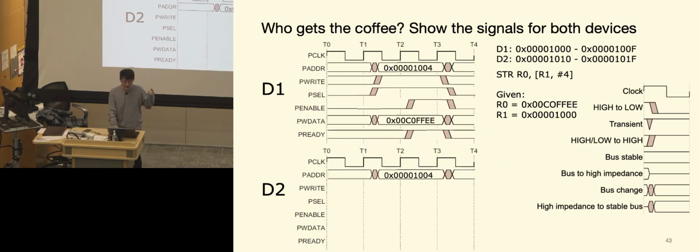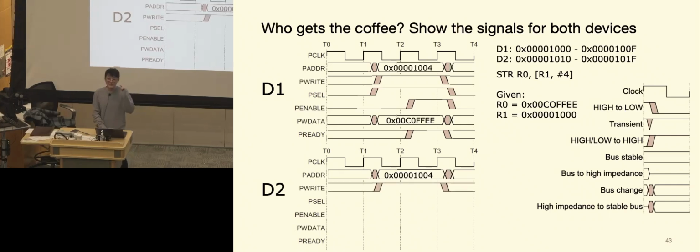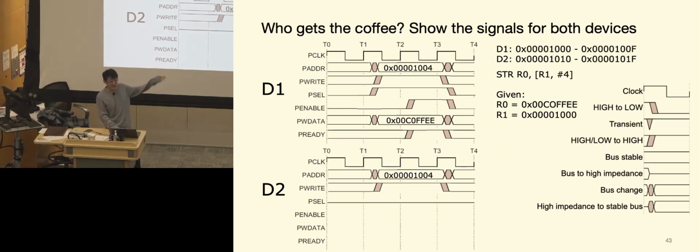And for the write, is that shared or individually assigned? The write signal, like if it's write or read. It's actually shared between all the peripherals. We will be using the select pins and others, which come up to this. The select pin actually is individually assigned. So for this one, it's never being selected, so it stays at low.